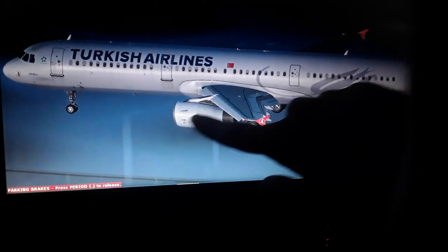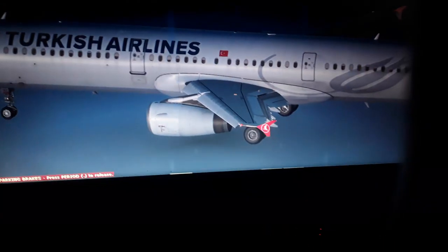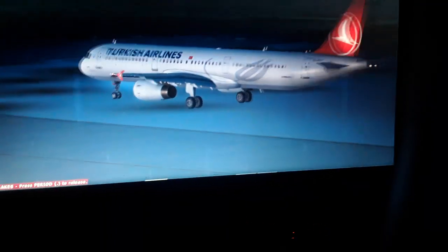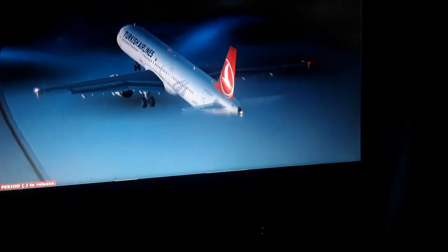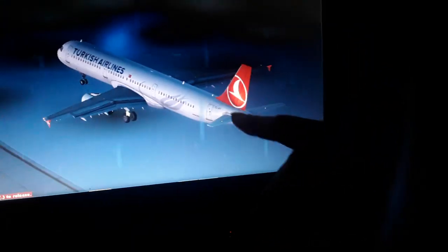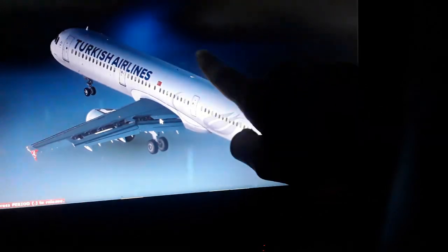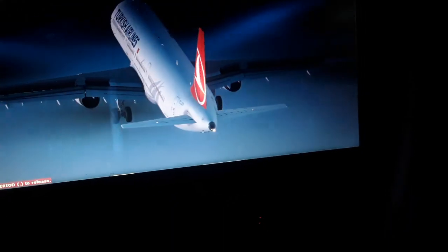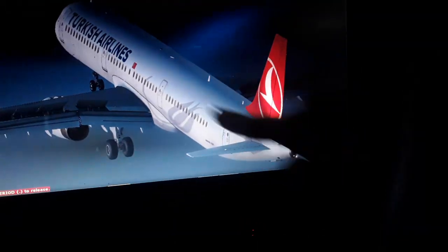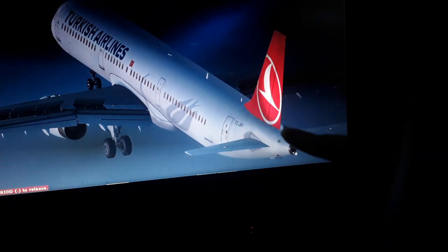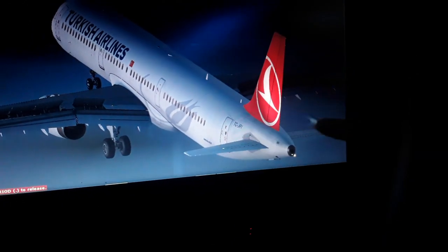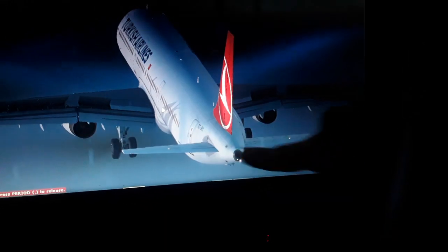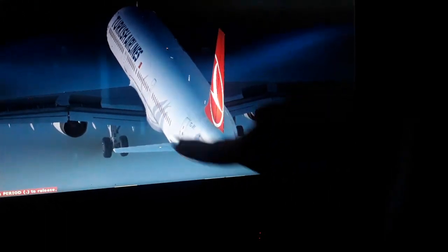You can see the engines, the CFM, the General Electric, the turbofan turbojet engines, which propels the aircraft forward. You're gonna see the engine start later. You can see also we have the moment arm or lever arm. The moment arm is the distance from the center of gravity all the way back to the horizontal or the vertical tail. So you can see it is times the distance from the center of gravity all the way back to the horizontal or the vertical tail over the surface area of the horizontal or the vertical tail, times the airflow of the air mass per second, times the Earth's acceleration of gravity.